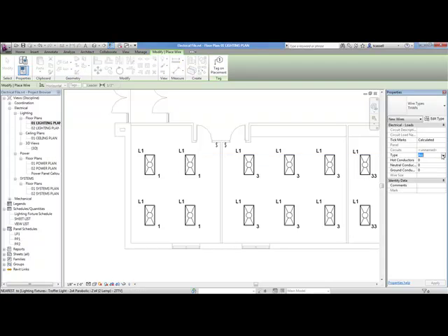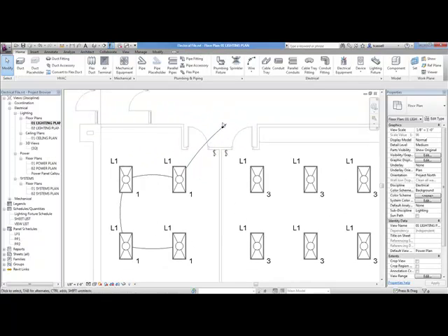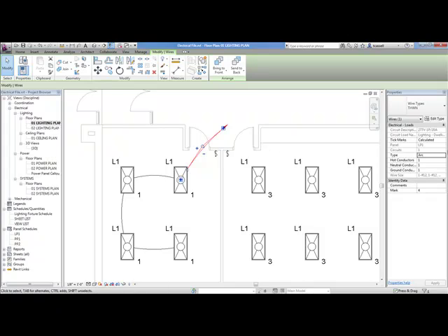So I'm going to create some arced wire where I will get these lights right here circuited together. You know what, I'll run these together here, and then my home run's going to run off in that direction, and so it puts my home run in. Now my wires automatically calculate their size based on the object they're connected to, and tick marks are either on, off, or calculated as well.